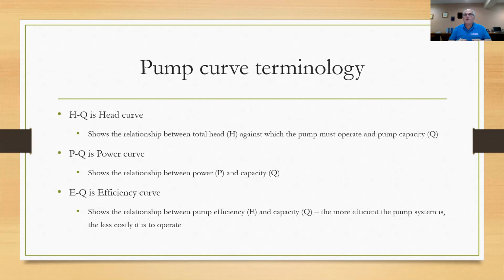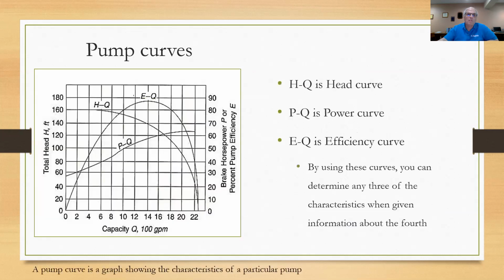And we'll see from the graph, when we're pumping at various flow rates, how efficient we become. In general, when you get a pumping system, you're going to find there's a spot right in the middle of the line where we want to be the most efficient, or we can be the most efficient. As we vary to either side on pump capacity, we become less efficient in what we're doing. The whole idea is to try to run the pump in the efficiency curve as best you can. Here's what it looks like.